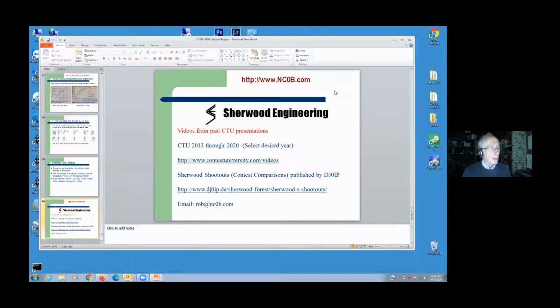Personally, I cut my long cords in half. I'm using Astron RS35Ms that have over voltage, over current, short circuit protection. The ICOM power supplies don't even have fuses. So if the power supply can handle a fault, I don't use fuses. And I shorten my cords by about half. If they're 12 feet long, I make them 6 feet long. So that'll help. But I also adjust my power supplies to about 14.5 volts. Makes a difference.